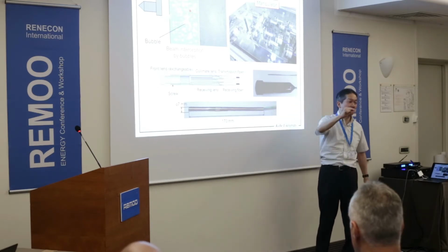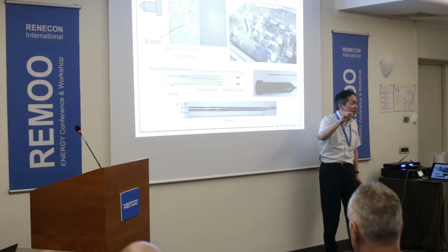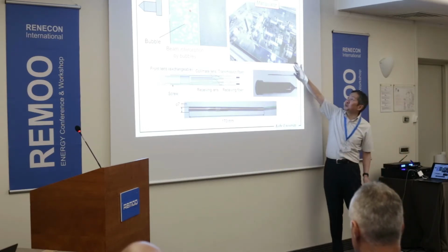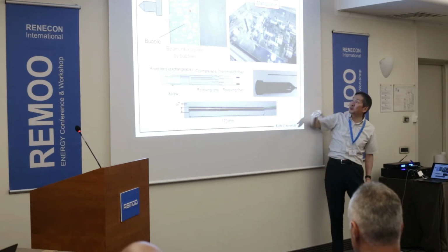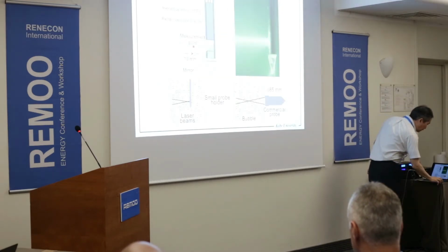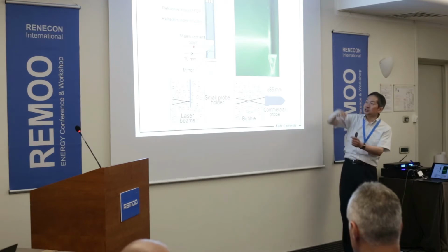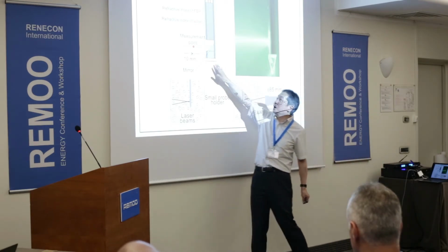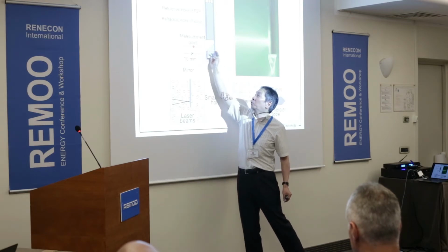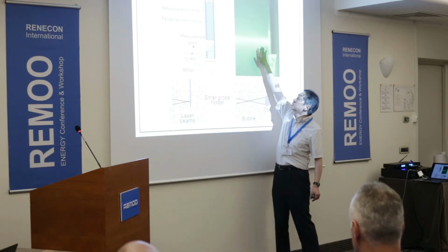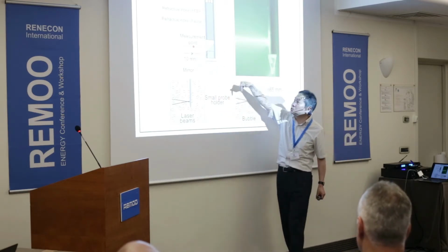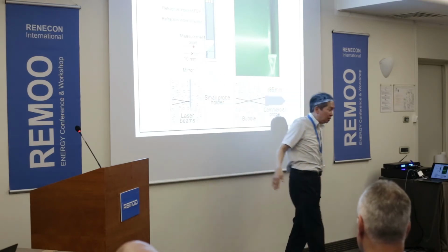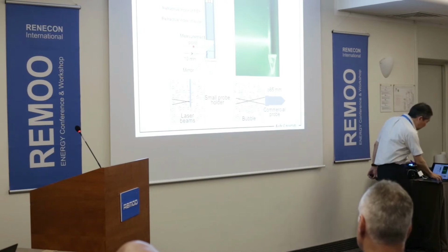The diameter is only 7 millimeters. The students made it by themselves, and we also made a manipulator of this laser system by ourselves. We insert this small LDV block in a tube, put the mirror here, and form the measurement point here like this. We insert this small probe directly inside the bubble column and measure the velocity field using this technique.